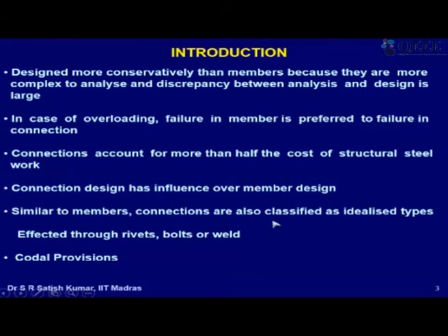Then similar to members, connections are also classified as idealized types, like rigid connections or simple connections. A simple connection is a connection where you transfer only the shear force. So you don't transfer any bending moment.